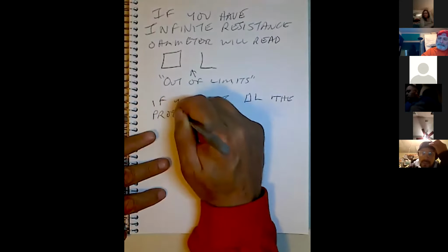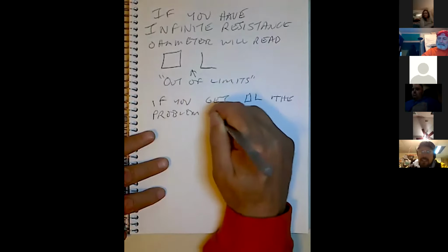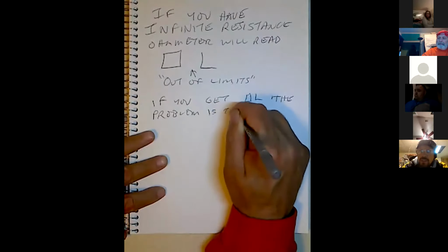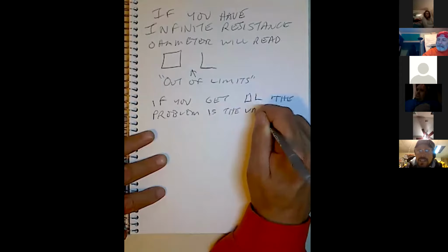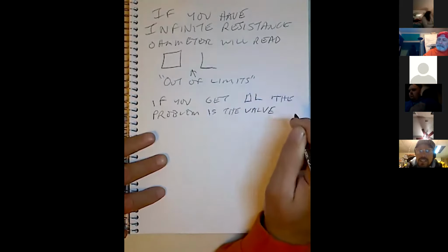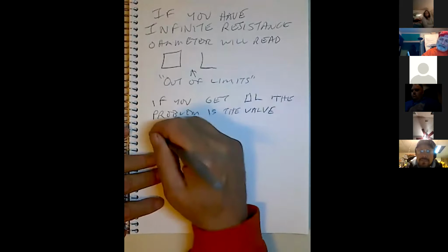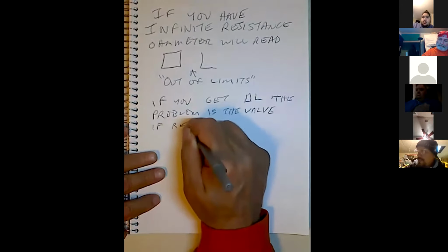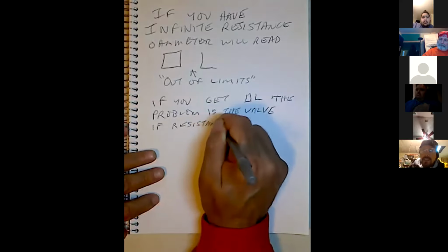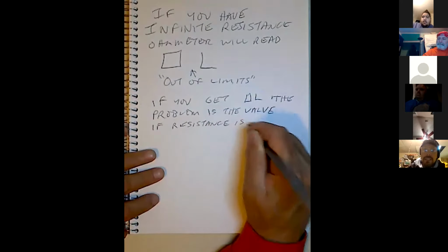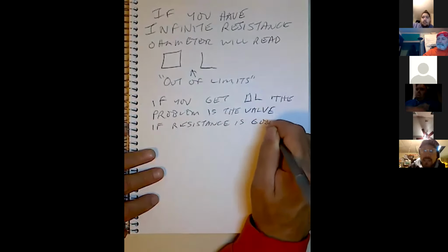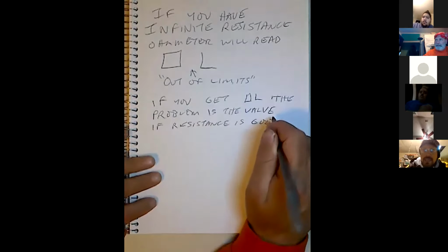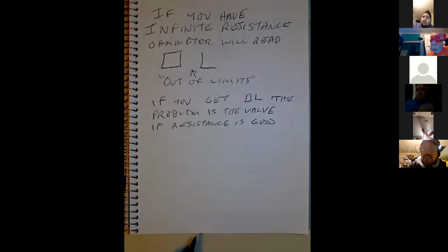So I think we tried to figure that out in class. So we know my purge valve works because Mr. Rowe checked it. Oh, that's right. So I went ahead and did some further research on it, and it read that it could also be caused from a faulty gas cap.